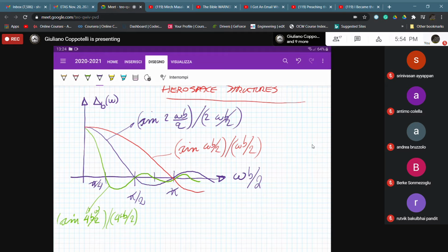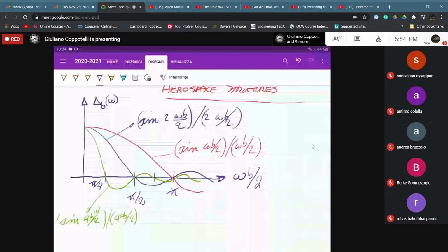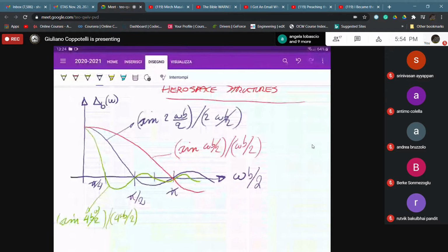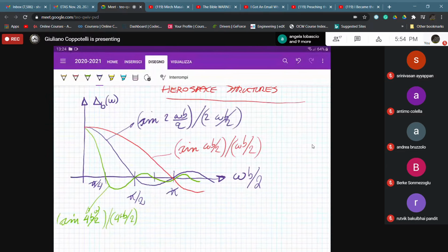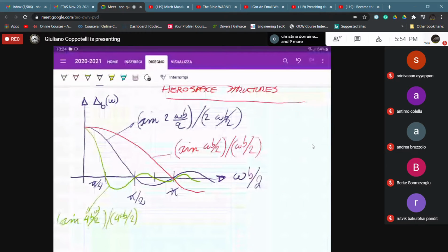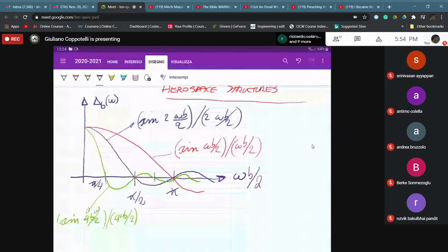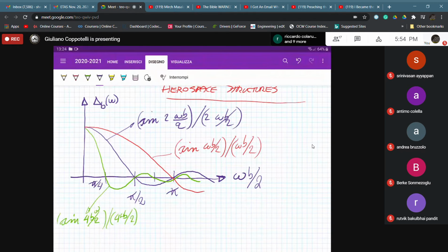We also consider that your B, the duration, depends on the hammer configuration. If you go back to your notes, you can see that this B depends on the mass and or the stiffness of your hammer. The higher the stiffness, the shorter is the duration time, and therefore the longer will be the wavelength. On the contrary, in this plot, the lower the hammer stiffness, the shorter is the wavelength.